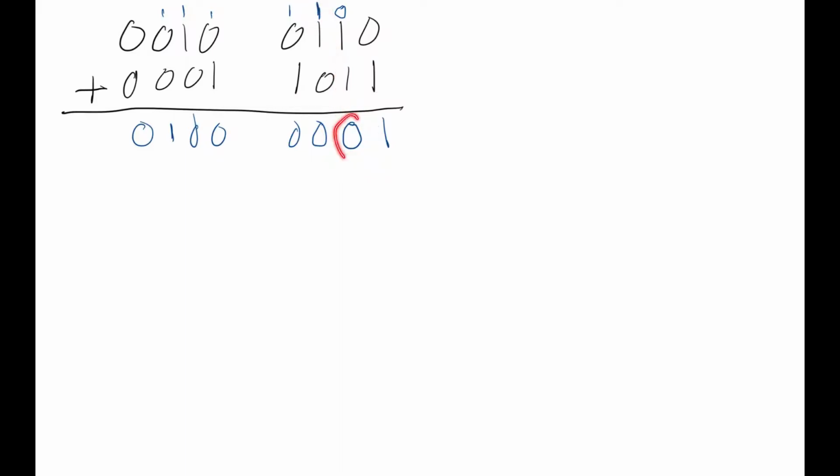We're going to take the carry out and feed it into the circuit that adds the next bits up together. So once we have a circuit that does this operation, so it takes in a carry in and two numbers, produces a result and a carry out, we can place 16 of them down and it will add a 16-bit number together.